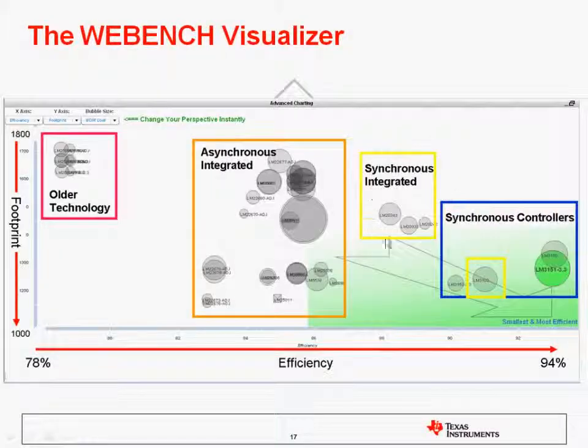Here we have synchronous integrated switch parts, which tend to have the benefits of higher efficiency, but they're easier to design with because they have onboard FETs. Here we have asynchronous integrated switch parts, which tend to be the easiest to design with, and their efficiency and footprint tends to be a bit more of a compromise. And then here we have some older technology parts, which I like to keep in the tool to show that as time goes on, parts do get better in performance.